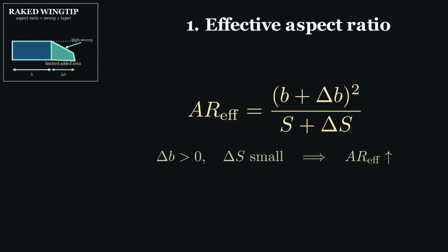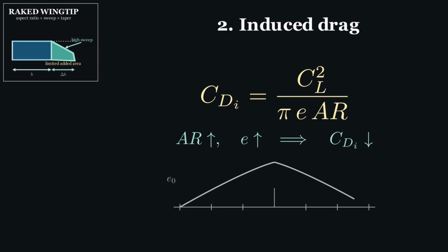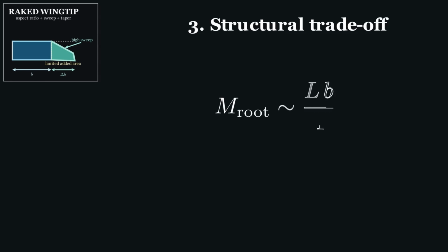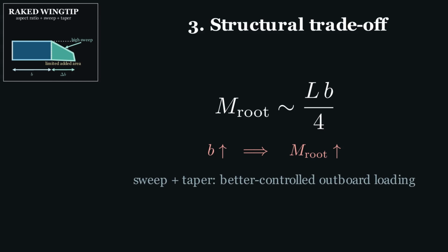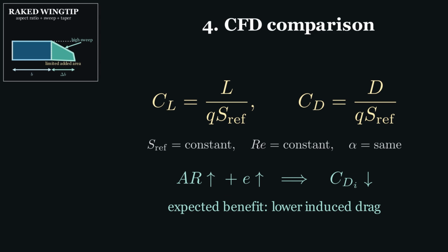Especially in high-speed flight conditions, this strategy perfectly balances structural weight and aerodynamic efficiency, making it a highly potential comparison configuration in our test. Given the swept configuration, the rake tip area is slightly larger than other tips, which provides a certain enhancement to the results.